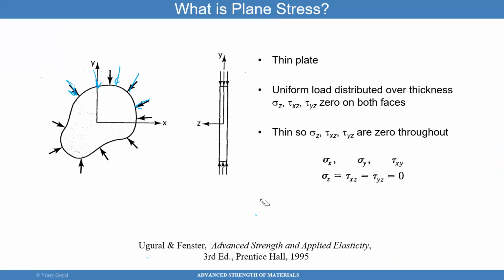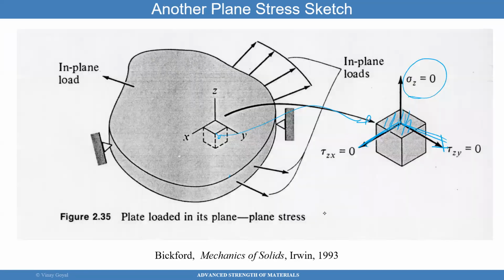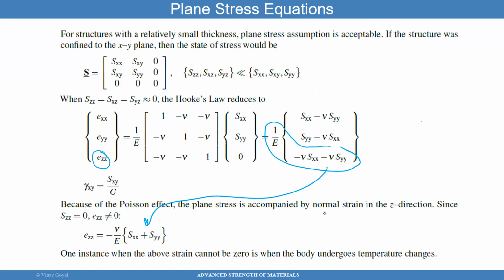So say I apply a load in the plane that you see there, this XY plane. If I apply a load this way to compress it, this thickness is going to increase in size. But that thickness is directly related to epsilon zz, partial w with respect to z. So clearly, that strain is going to matter.